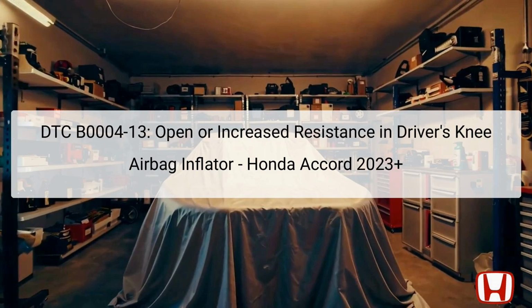Diagnosing DTC B0004-13 involves understanding the specific malfunction linked to the driver's knee airbag inflator in the Honda Accord 2023 and newer models. This error code indicates an open circuit or increased resistance within the driver's knee airbag system, which is crucial for deploying the airbag in the event of a collision.